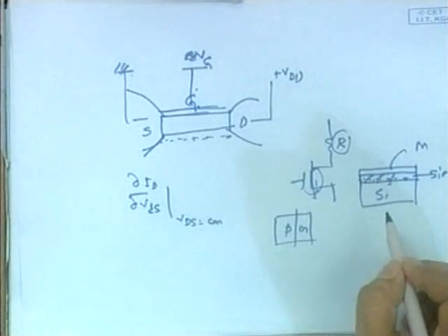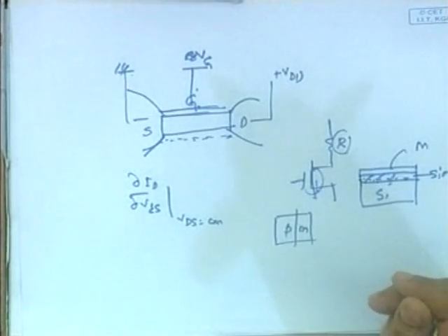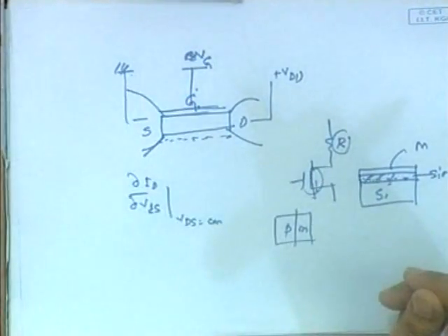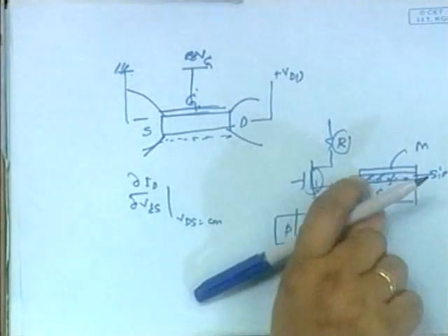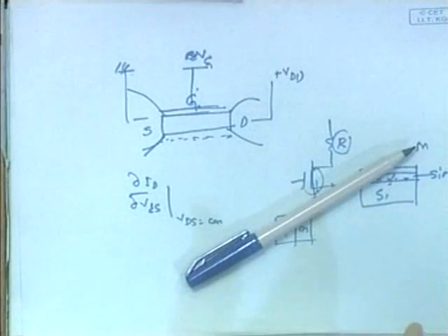The channel is full of charge, the mobile charges. They get attracted to those traps, and they are constantly trapping and detrapping in those oxide traps. They actually constitute the 1/f noise. You can understand physically what happens if the frequency is high. The charges are modulated at high frequency, they are modulating pretty fast. The trap centers have a certain escape or attempt frequency, because trap centers will trap and detrap, and they need some time, right? That is the response time. If the operating frequency is much higher than the response time, then my trap centers are less affected.